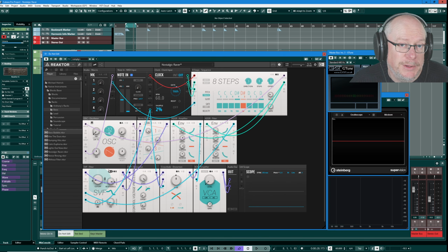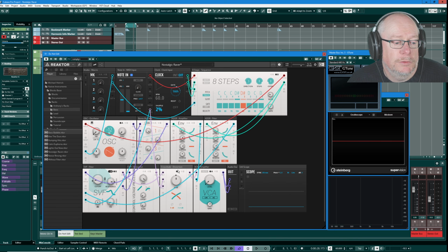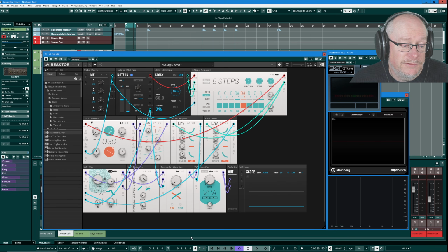Now there's a load of cables going into and out of this filter, so it's a little bit tricky to see, but basically we have a cable coming into this crossfade module and a second cable going into this control voltage processor module. Let's deal with the input 1 first, the one that's going into input 1 of the crossfade module. If you've never come across a crossfade module before, they're incredibly simple. On the left hand side of the fader, we take our entire signal from input 1. On the right hand side, it's fully input 2, and in the middle, we mix these 2 inputs together.